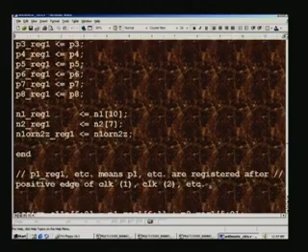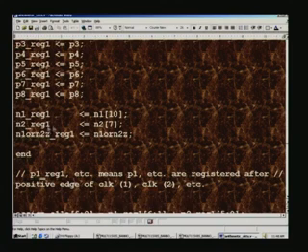And so also for the n1 and n2 sign bits. This is the actual n1, and this 10th bit is the sign bit. So we preserve that as n1 reg 1 here, and n2 reg 1 here for the sign bit of n2. We also preserve whether the product is 0 or not, and this we have to propagate at every stage, because we are going to use it only at the very end.